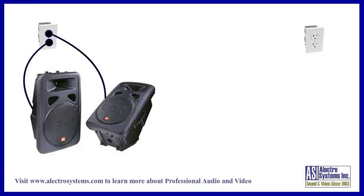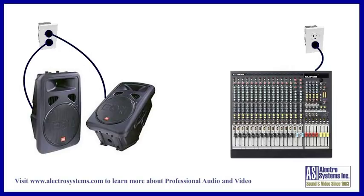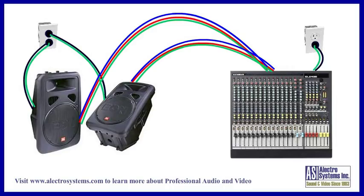But what about when you don't need to convert from line level to mic level? You can't use a DI box for these cases. For this example, let's consider the powered floor monitor. A powered monitor is just a speaker with a built-in amplifier. We could just as easily use a computer, mixer, amplifier, or any other line-level combination as our example. Again, the mixer and powered speaker are plugged into different AC outlets and interconnected using a balanced audio cable. The mixer output and speaker amplifier input are both line level and balanced, so we don't need to do any conversion. We just need to decouple the grounds.